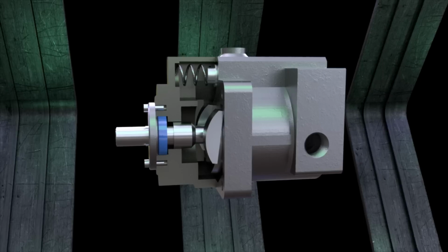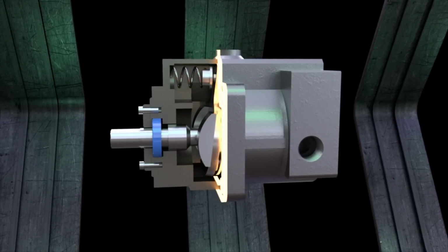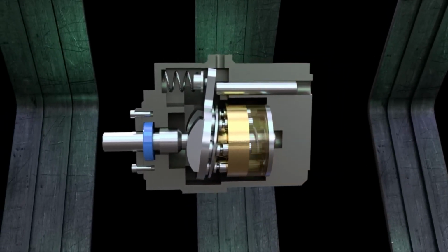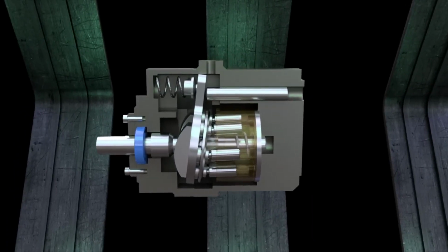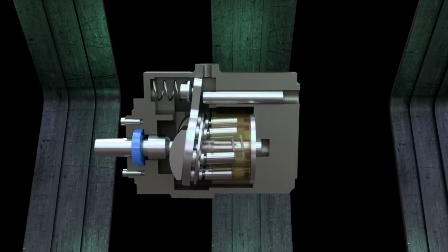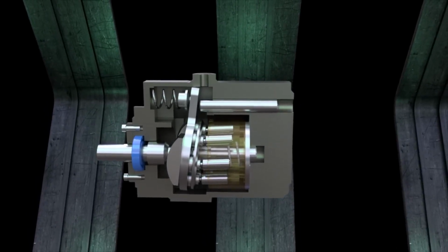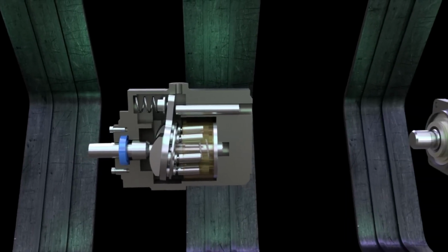In axial piston pumps, the pistons are parallel to the axis of rotation of the shaft, or slightly inclined at an angle of not more than 45 degrees. To pump fluid, the pistons in the pump must move forward while the drive shaft rotates. Converting the rotational motion of the input shaft into the translational motion of the pistons is possible due to the inclined position of the bent axis, or the swash plate on which they rest.